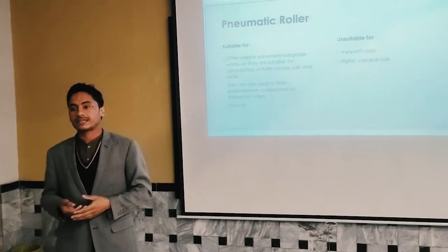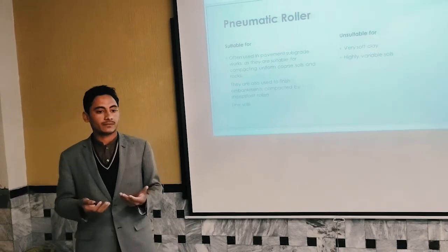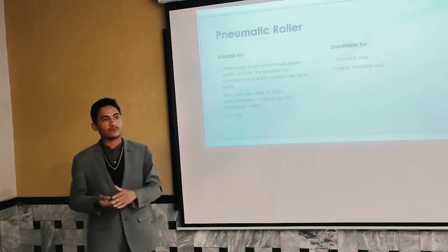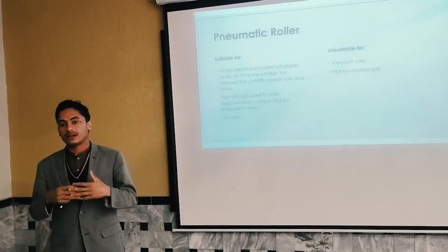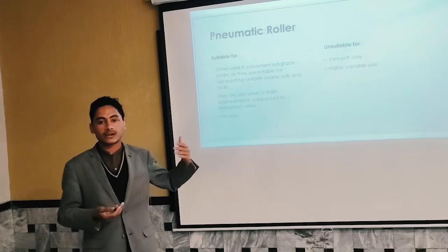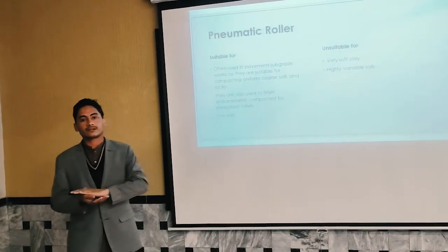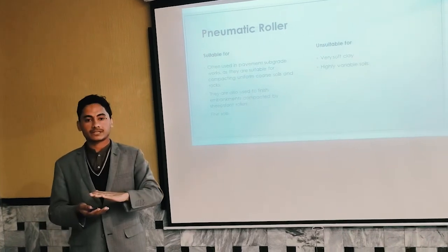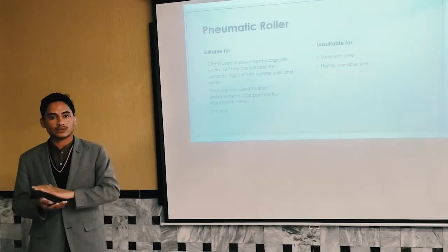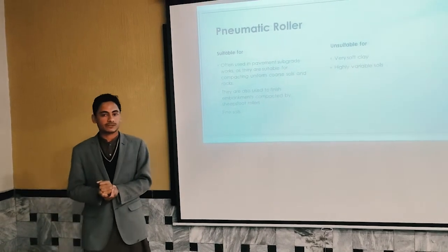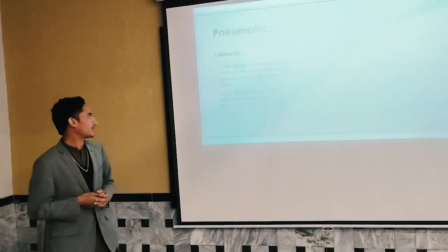And the second one is the disadvantage: if somewhere the moisture content is more, we can't use this because the tires cannot get proper friction. So when there is no proper friction, there will be no compaction. We can't get a good compaction.